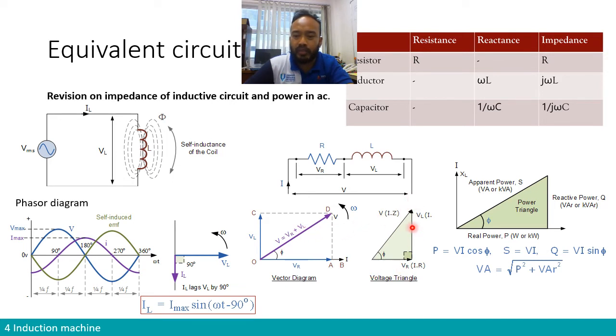So this is what we call voltage triangle, a component of voltage that is created due to the resistor. So it's a relationship between current and resistor. There is a component that's perpendicular to it due to basically the reactance. So in this case, it's only inductor. This is what we call as a reactive part, and then both of them create the total sum of those vectors. Basically, the real voltage. It has a lag of phi behind